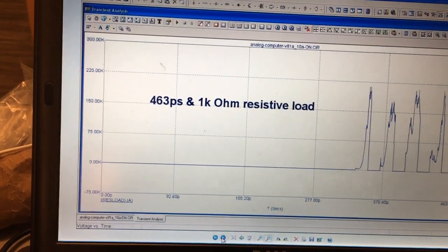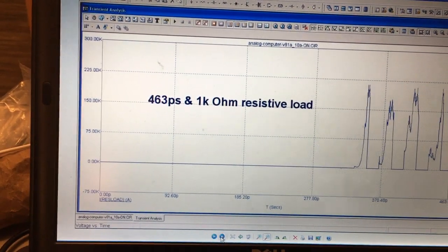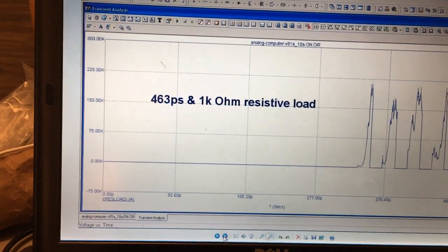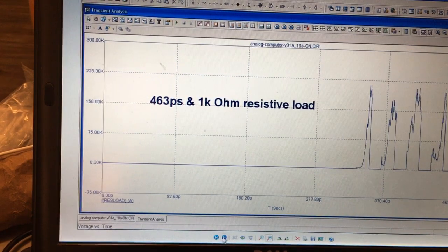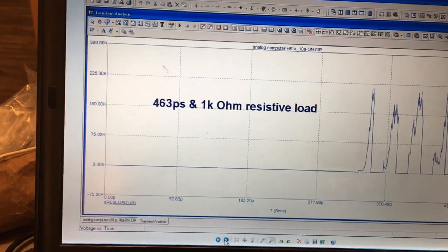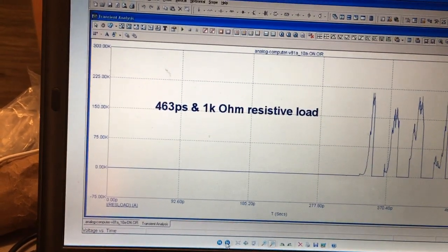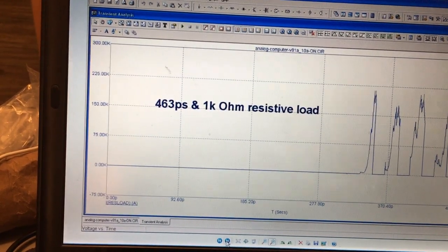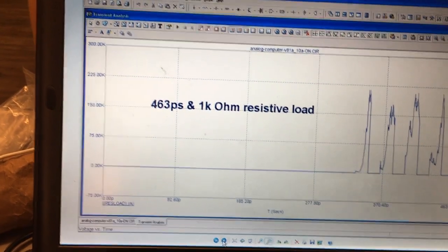So if the circuit is erratic every time you run it at that point, giving you different results, probably the simulator would be giving you matrix is singular results, because I think they are equivalent realities between the simulator's reality and the real world reality. So that's why I try to avoid all errors, because they're there for a reason.